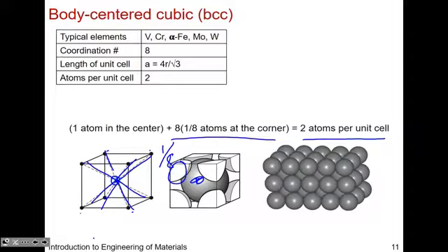Yes. So you could see, this figure is from your book, and it does a good job of showing the lattice points, okay, where you have half, half, half here, and then you have 0, 0, 0, but that's translated. So you have the atoms at the corner, okay? And then here it does a good job showing the fractions of an atom that's at the corner, and then this is just all the atoms propagated. It's not a very useful rendering because they're all just like gray balls next to each other. But I think these two are much more helpful to help you visualize.